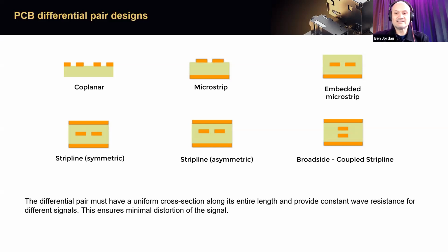You know, back sort of 15, 20 years ago, before differential pair routing was possible, a lot of people did their diff pairs for Ethernet, for example, on a circuit board using broadside coupling, because you could route the true on one layer and then make a copy of that and paste it onto the very next layer down in the layer stack. And that's how you would do the complement.